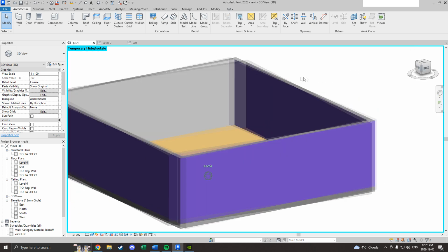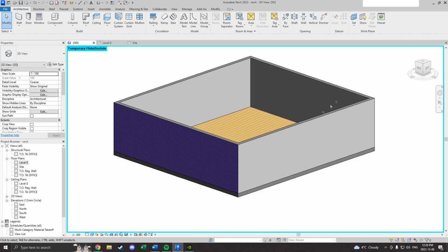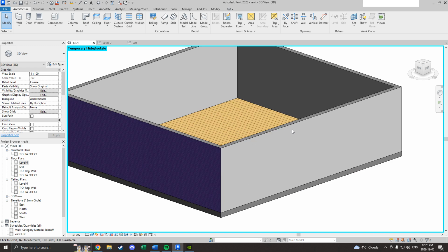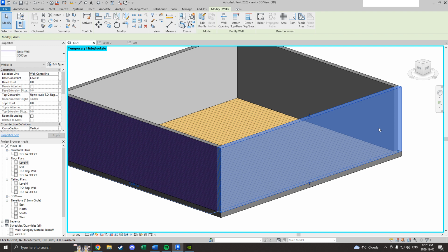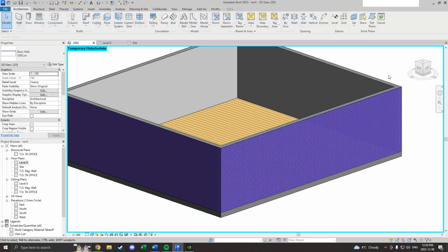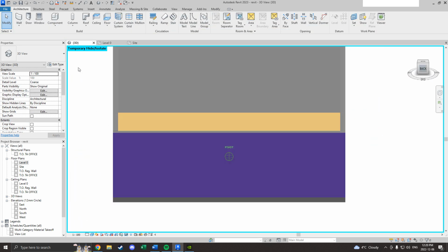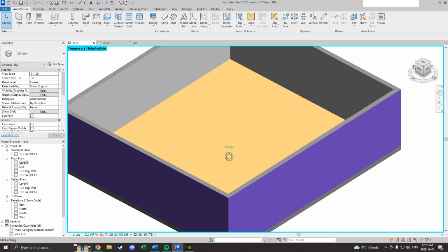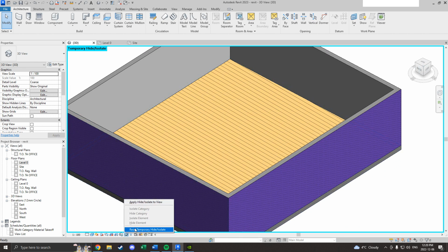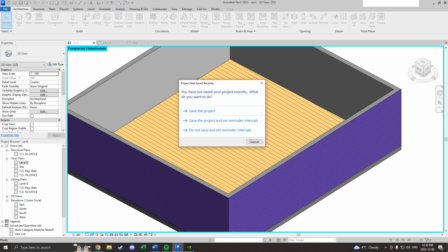Let's look around our building. And this is a common issue. Well, depends. It was an issue for me. I had a wall that was interior facing exterior, which just really depends on how you lay it out in your level. So, simple fix: you just click on the wall element you want to change. You press spacebar once and it flips the wall. And there you go.